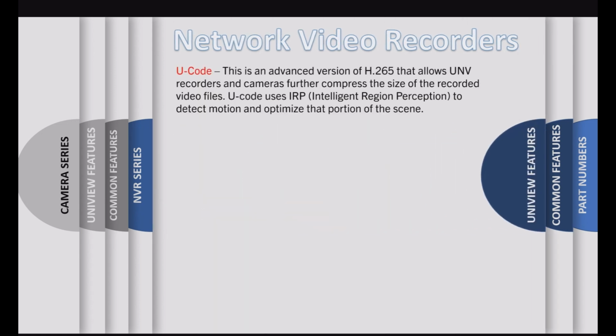So as we move into the Uniview features, these are things that are specific to Uniview recorders or Uniview recorders that are used with Uniview cameras, as UCode is. UCode is an advanced compression algorithm used with the H.265 compression that's gotten pretty standard now on IP cameras. And what it does is it realizes what portions of the screen are dynamic and which are static, and compresses those static images to really reduce the file size, gaining you quite a bit more time on your hard drives than you would without the feature.